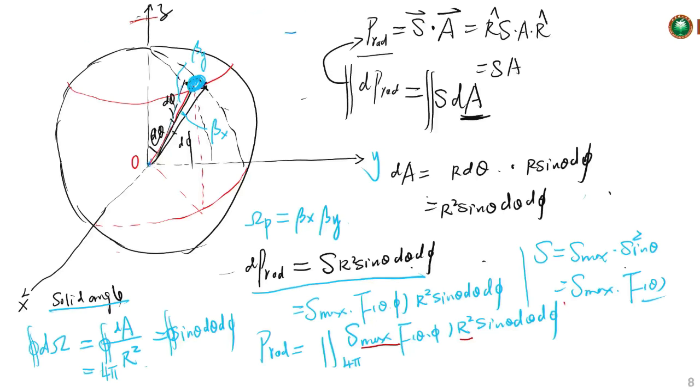So, for example, if we know our antenna, it usually gives us its beam angle at the vertical polarization and at the horizontal polarization. So we can multiply both together to get the solid angle like that. This is just a method to simplify your calculation.